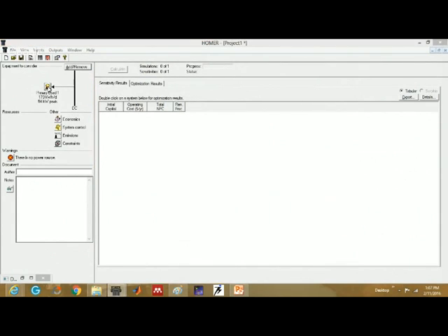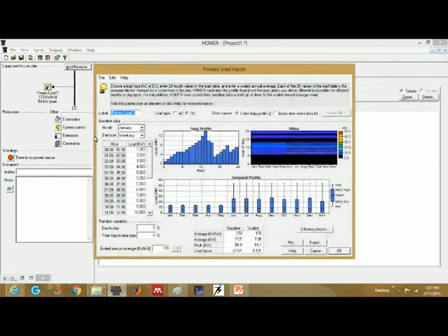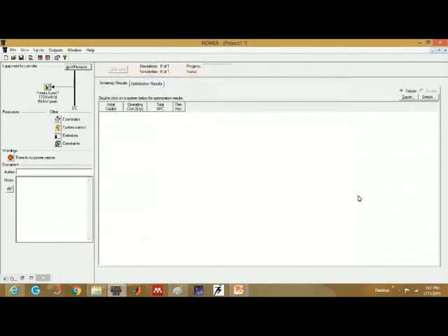This is 170 kilowatt hour per day load. Peak is 54. No variability is there. Nothing is there. I just want to design my system according to this DC load. See, right? So next part is how I want to meet this load, what I am going to apply. Suppose I want to, first I will take the example of solar photovoltaic, right?